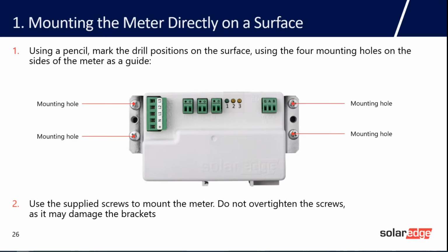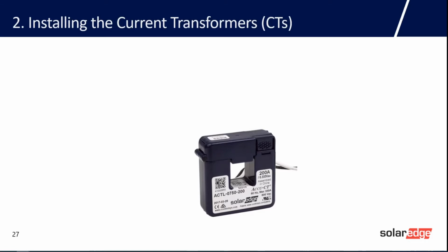Current transformers, or CTs, are devices that help measure the alternating current flowing through the power lines. Before we begin, it is very important to place the CT in the correct direction. Incorrect orientation of the CT will cause wrong readings, and malfunctioning LED indication on the meter. Take a look at the figure, and make sure that you identify the arrow shown on the CT.